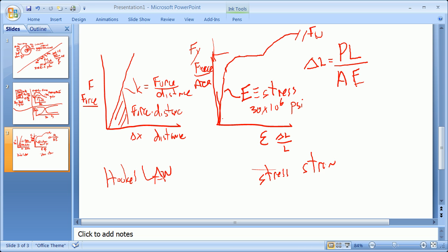with in fact knowledge that most steel has the same modulus of elasticity, but many concretes are going to vary based on the strength. But most importantly, realize that the value, in other words the strength, the stiffness, and something called the toughness, which is the area underneath this curve, all have the same units of stress. So that curve is a large manifestation of that curve speaks to a lot of engineering, especially when you start trying to keep things down here in this zone so they bounce back to where they started. If in fact you do take something beyond this yield point, the material generally will rebound in a line parallel to the elastic, and you have something called residual strain.